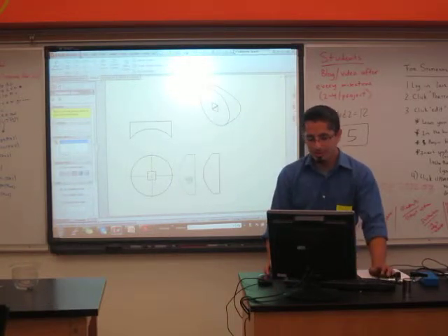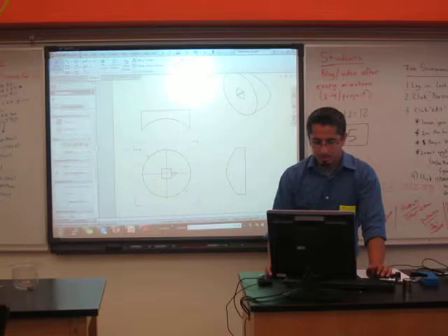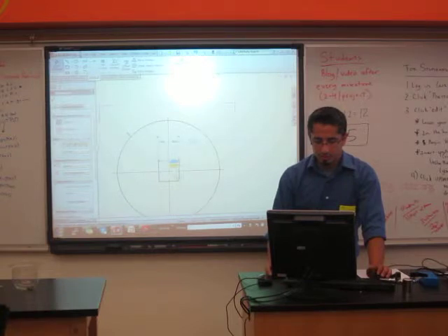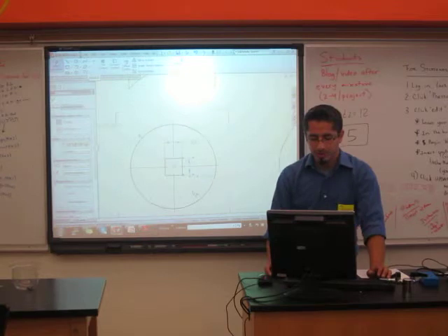Well, so all I want really is these 3 views. Let's see if we can get some of the other dimensions to work. But the critical ones here are I need to know the overall, that guy. We'll probably need to know the width, about 0.5. And then I don't know that this thing is square. Nothing told me it's square. So you have to specify that it's square, either by saying square or by saying 0.5, 0.5. Because it's all centered, but I might not even know that's centered. We'll assume it's centered.